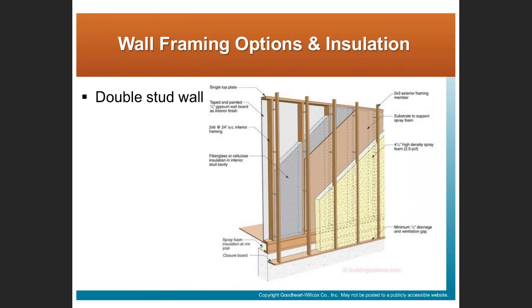This is something called a double stud wall. Again, the same idea. Right? We have a structural wall, and then we have a separate non-structural wall, and the space between the two gives us additional space for insulation, additional ability to make the building more efficient.